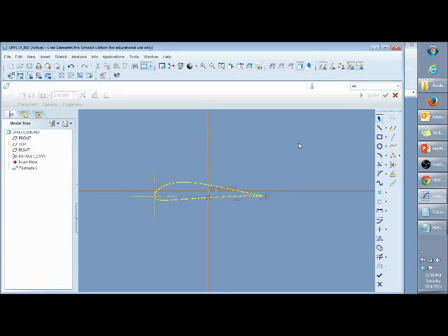A very important step to make sure that you have everything good and that the extrude won't freak out on you, because Elements is really good about telling you that there's something wrong with your sketch before exiting out of the sketch. Creo, not so much. There are several useful tools right up here that will help aid you. Select these two. I use those two most of the time, and you can select that one too, but it doesn't stay highlighted.